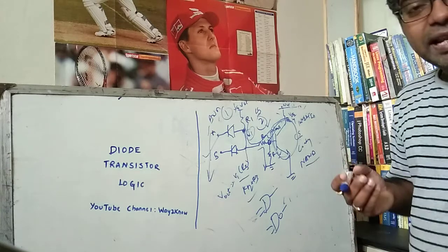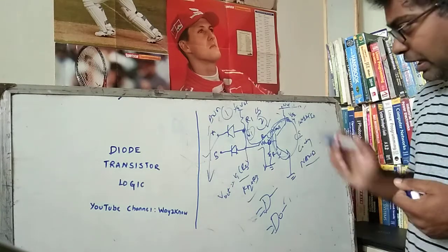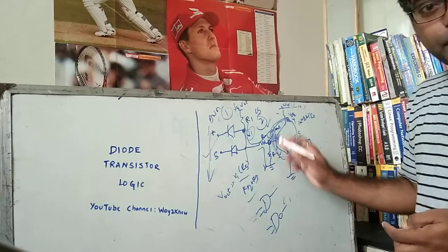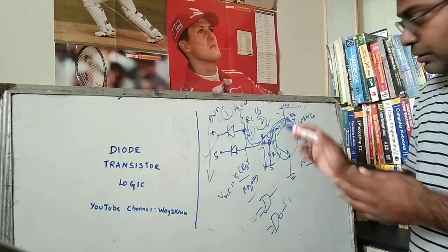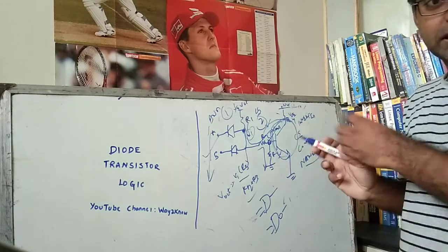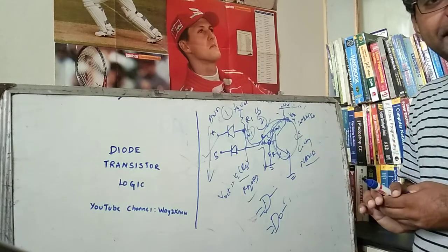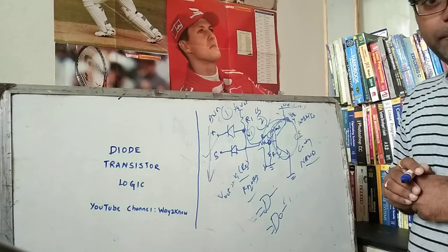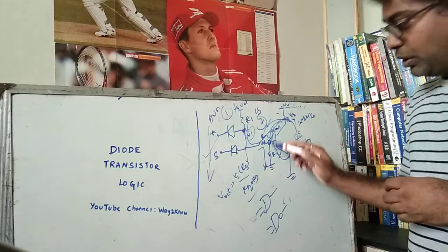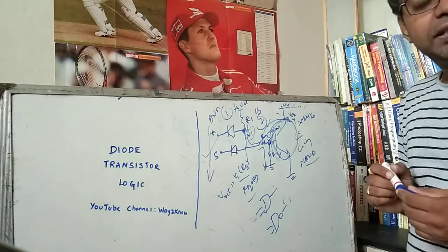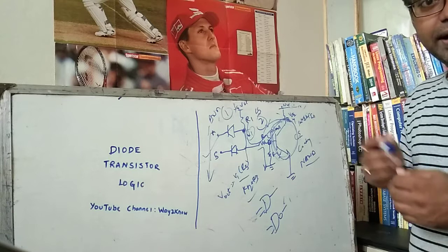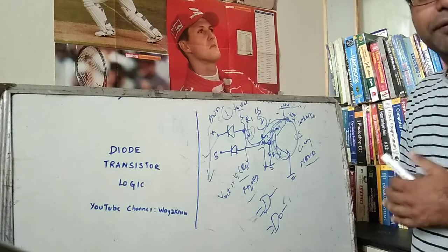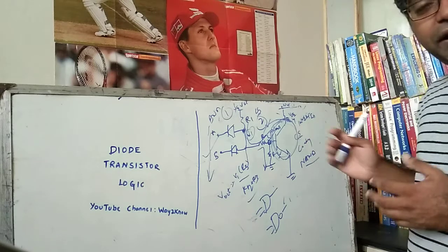So that delay adds up. There are different ways that designers handle this, where they employ a Schottky based diode, taking the collector voltage and feeding it back to the base, so that you don't drive this into the saturation state and still the common emitter inverter functionality is maintained. So there are different ways.